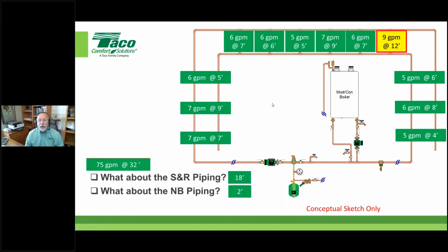and that calculation based on the pressure drop of all the extended piping will, of course, include the equivalencies for your valves and fitting factor as well. We're not using a factor. For more accuracy, we want to estimate. If we have no idea, then we have to use a factor. Generally speaking, we'll use a 1.5, a 1.4, sometimes higher if you feel that's necessary. But you realize valve and fitting factors are nothing more than WAGs. And I'll let you guys fill in what a WAG is.